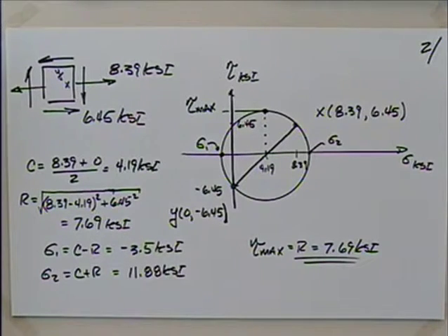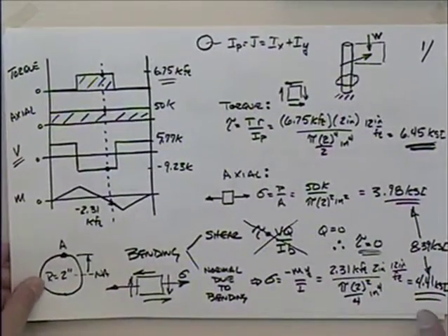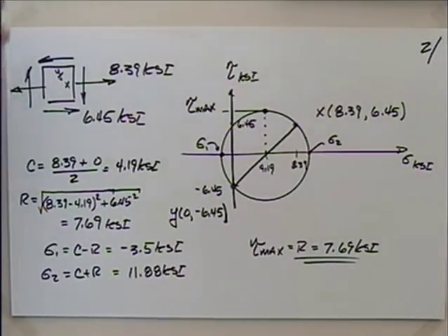So you've got some homework problems on this. They can be fairly involved. That's good from the sense that it gives you a lot of review of what we've done over the term. Then we put these stresses together, and we can even take it further onto Mohr's circle and then start to talk about what are the maximum possible stresses there if we start to look at different orientations.